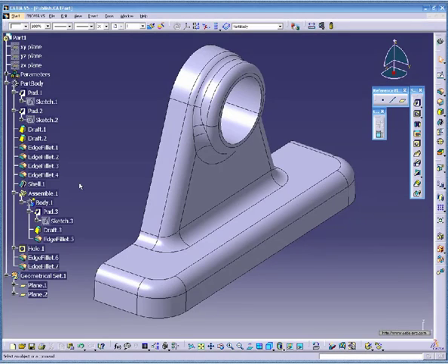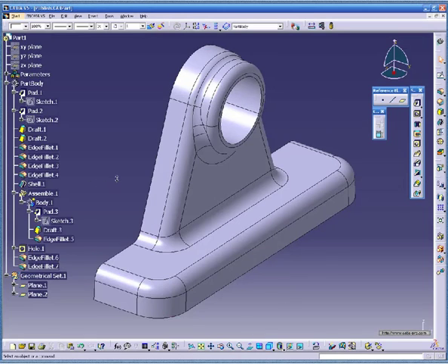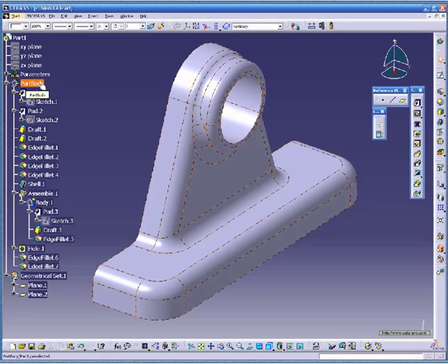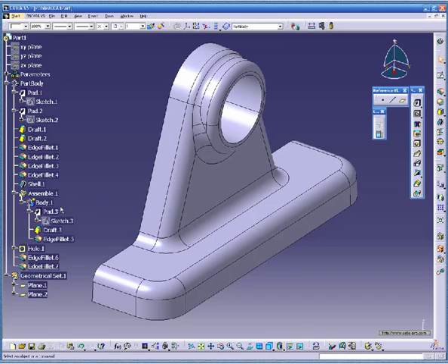Okay then, let's see the benefits behind using these kinds of folders, starting with bodies. We use this type in order to simplify a complex design. As you see here, this side is the most difficult one in creating this part. Then to make it easy to be done, the easy portions are produced inside one body, called part body, while the difficult ones are created separately in body 1, and then assembled to the first body.